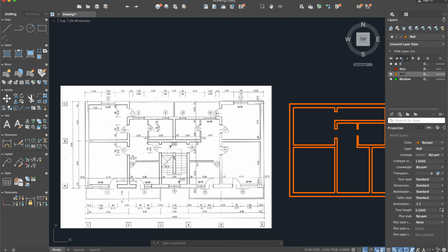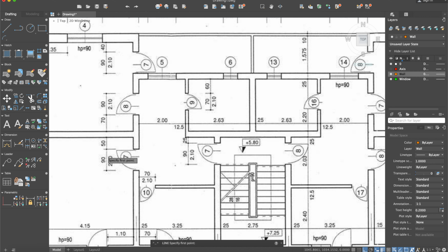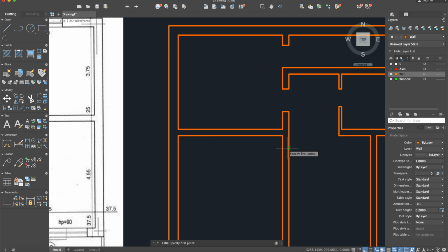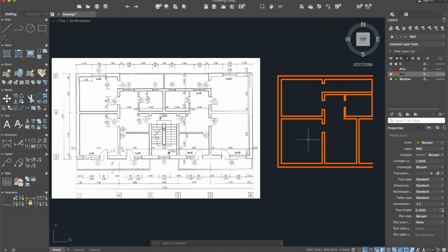So the next step, we have here another door. Okay, so 50 and 90. For this time, here we have another line, offset again 50, and offset again 90. I must delete this. So trim, select everything, and here it is, the next door. I will put all the doors at the end before mirroring.